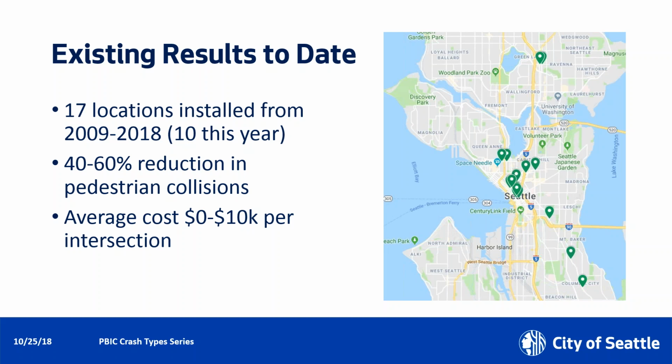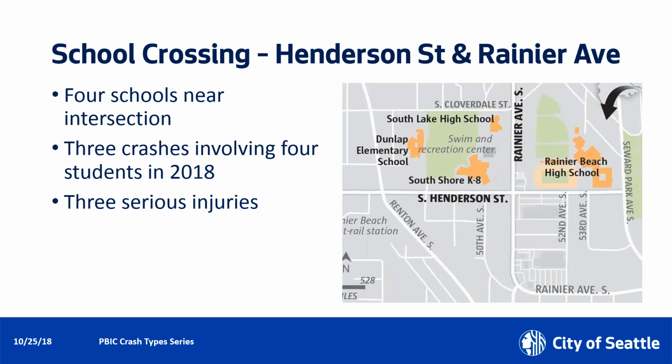If you're looking at a standalone project, there is probably a cost associated with physically being able to retime it, and maybe you have to replace some pedestrian heads, or a controller has to get swapped out because it can't handle those extra phases, especially in areas with older signals. But typically still one of the cheapest things you can do that has a high safety benefit.